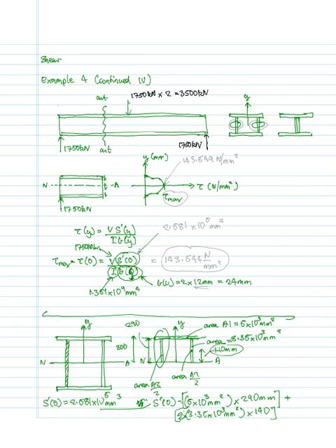And we need then to add on another one for this area there, but that's going to be identical, so I'm just going to put a 2 times in front, and then if you bang that through the calculator, the whole lot S-0 is going to work out to be 2.681 times 10 to the 6 millimeters cubed.